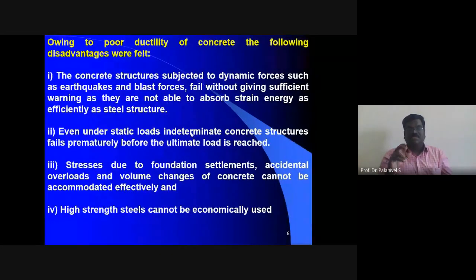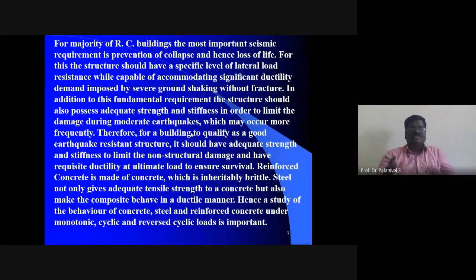Stresses due to foundation settlements, accidental overloads, and volume changes of concrete cannot be accommodated effectively, and high strength steel cannot be economically used. These are the disadvantages felt due to poor ductility of concrete. Okay, how to overcome them? I will just read out this one.